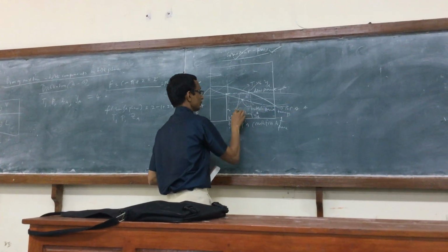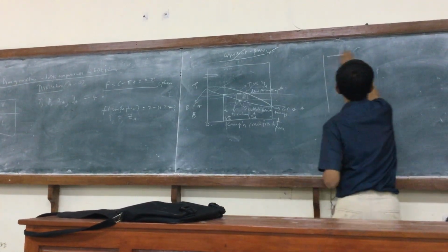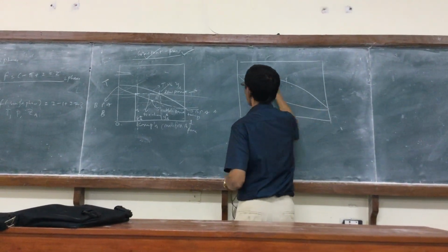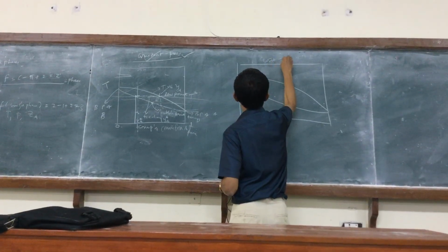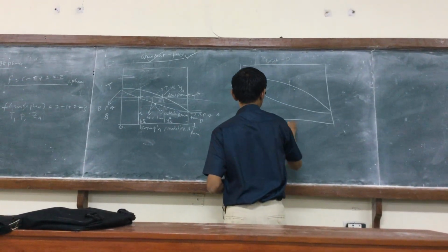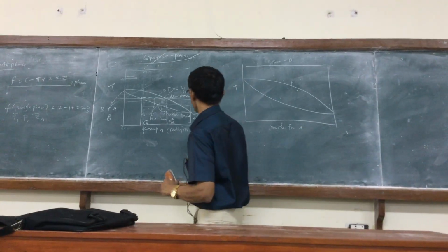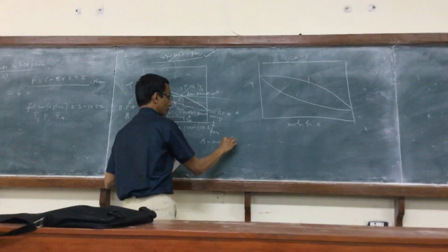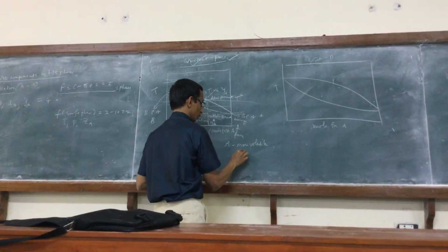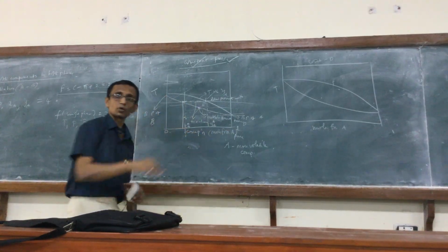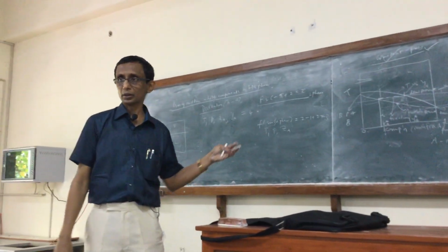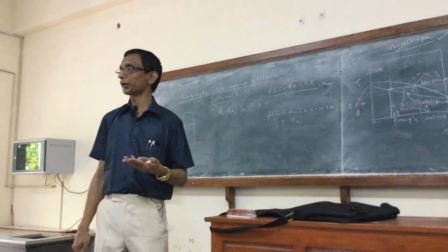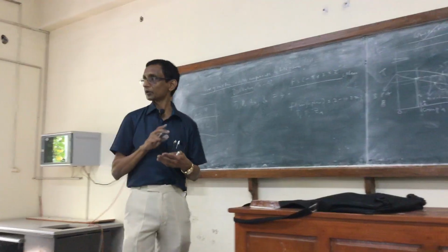The reason given often is that suppose we draw it in a parallel manner here, and we plot it like this, constant pressure, temperature, mole fraction of A. The A here is referred to often as the more volatile component because its boiling temperature is lower than that of B. It means that we start boiling at a lower temperature at this pressure.